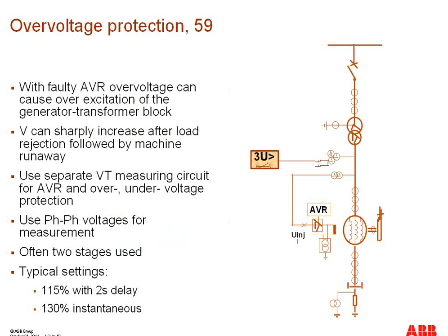So several conditions. Typical settings are 115% with 2-second delay and 130% instantaneous. This function can also be used for open detection or switching on and off of the reactor or capacitor when combined with the directional reactive power function.